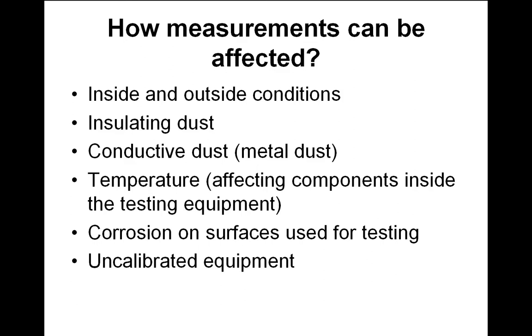You've got dust as well. A lot of dust is insulating. So when you've got dust settling down, you take a measurement and you're just sitting on top of the dust. It could affect your measurements. And then you've got another nightmare, which is conductive dust.